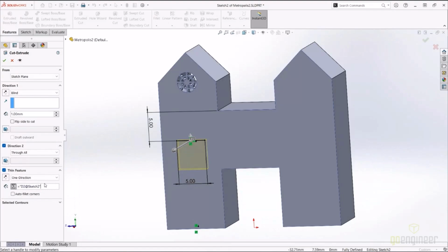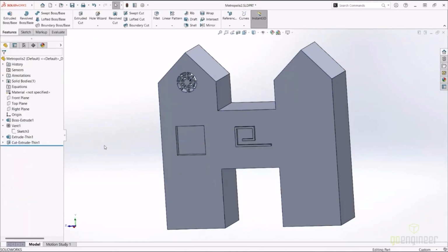But that's a bonus. The fact that I can put that right, like, you couldn't put an equal inside of a sketch. If I drew the other 3 lines of the square, I could put an equal sketch relation. Well, I could just put an equal right here, equal to that dimension. And then again, maybe the information that I know is at the midplane of it. Again, that one is a little bit extreme. I don't know if I would just go for a line versus a square inside of a sketch, but I want to get your wheels turning and thinking about that it is a possibility.